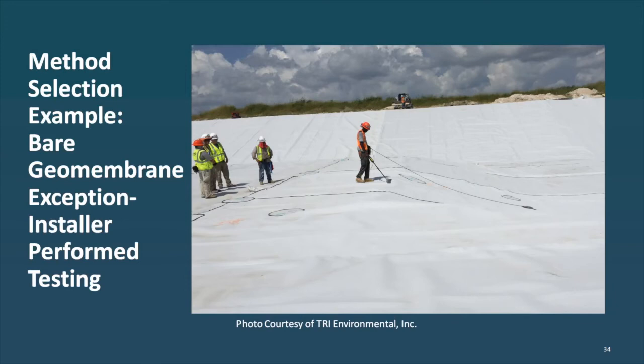And the thing is, the water puddle test is always a third-party test. Liner installers don't have water puddle method equipment. It's not commercially for sale. It's a little bit more difficult to operate. It's slightly tricky. It's subject to some site conditions. It's not a super simple test to do. However, arc and spark testing are very simple tests to perform. In fact, spark testing has been done by installers basically ever since the birth of that conductive geomembrane product.